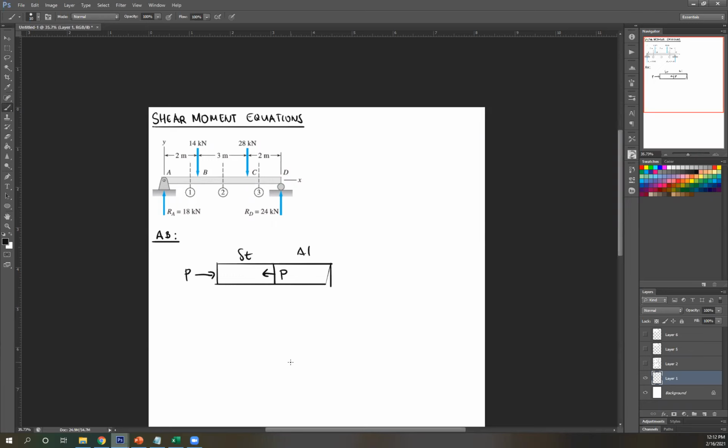No one? Right. So the answer here is, again, from what you've been doing, you're gonna cut, isolate, right? That's what we've been doing. So cutting steel, draw the applied force, then you're gonna guess your internal force direction. So make an intelligent guess. This needs to be in equilibrium. So I'm gonna guess this is the internal force for steel towards the left. And then you do your free body, your equilibrium equations.